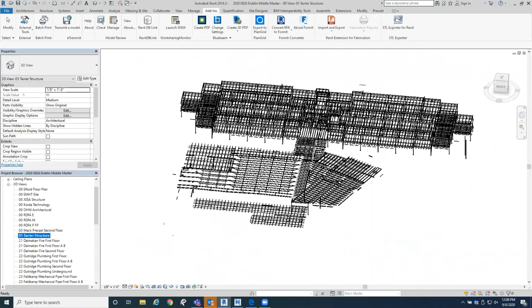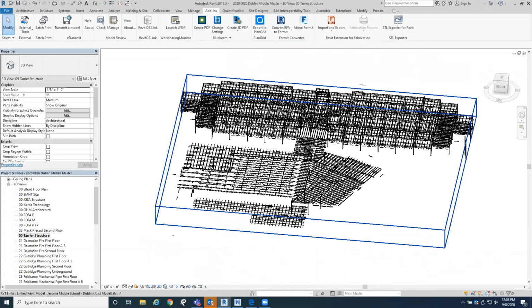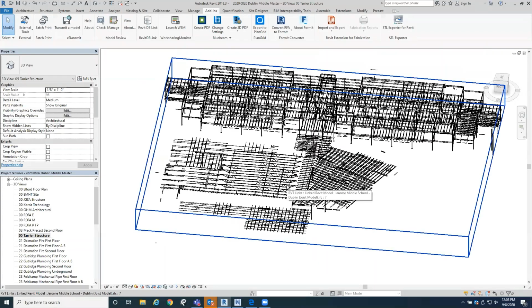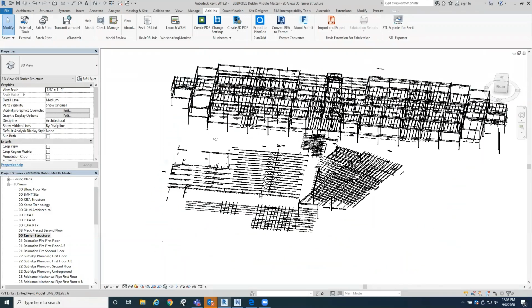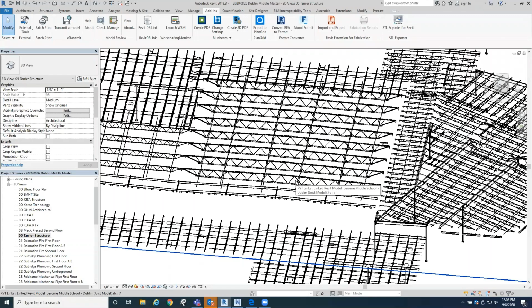Our structural contractors, we do ask them to contribute a structural fabrication model, and we ask them to give us the joist fabrication model, because there are times that we are trying to go through the webs, and generally our structural engineers, I think, are more comfortable if we're loading the trusses from the panel points.